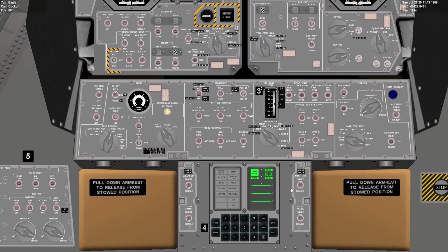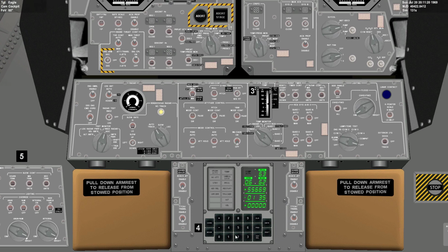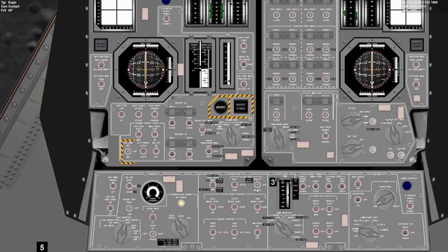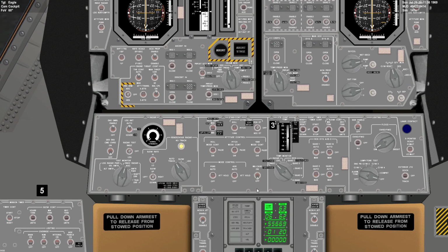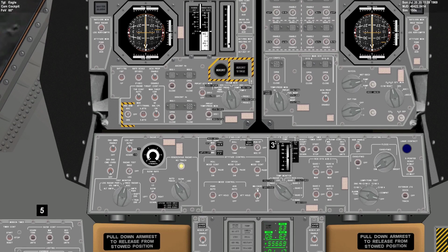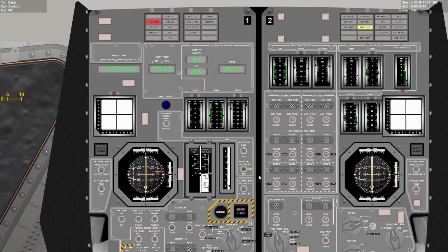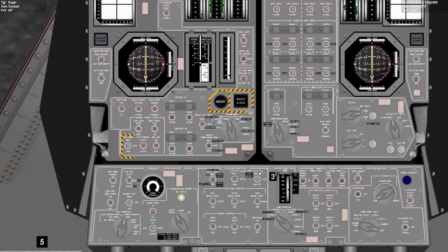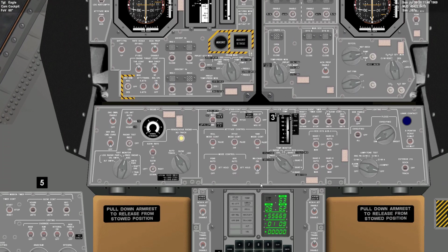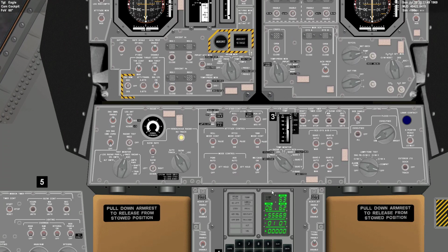The other big thing that I added is the hand controller. So I have a rotational hand controller here, the ACA, the Attitude Control Assembly. We load rad modes. Go 2 and turn off minimum impulse. So the hand controller was kind of complicated to add. It goes into the AGC through the crazy analog digital converter and the interface modules from the resolvers.